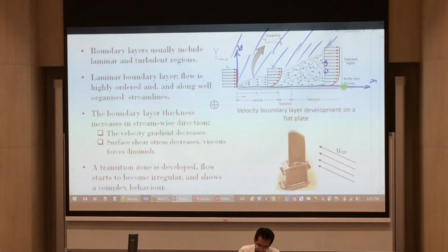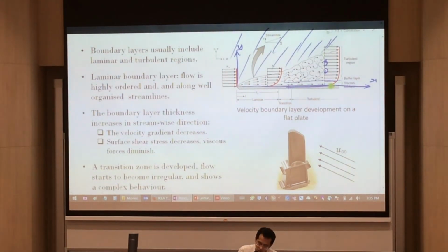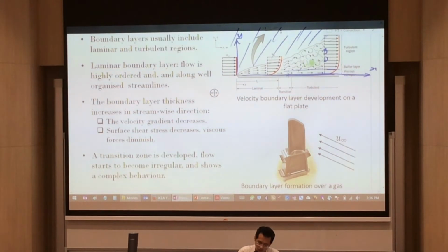Right. Now, what I want you to see is this region over here. This is what we call the viscous sublayer. And this is already in your turbulent region. And it's actually laminar flow that's going on here. A very, very small little region on the turbulent side. So if you were to look at it, this is actually a good region that we'll be using, even though